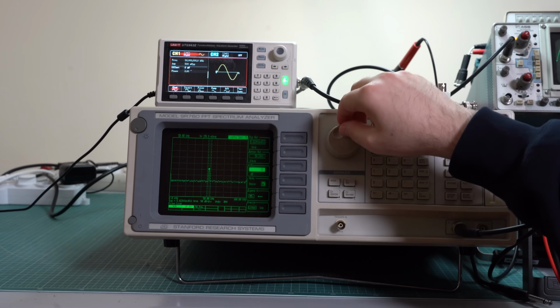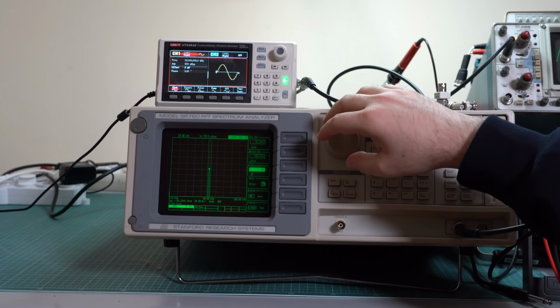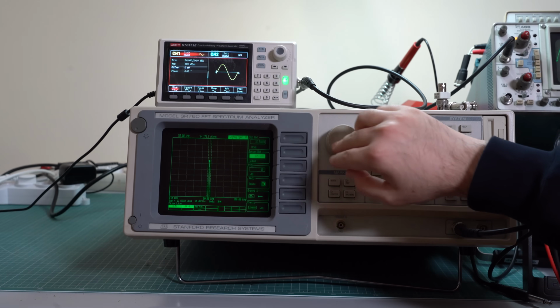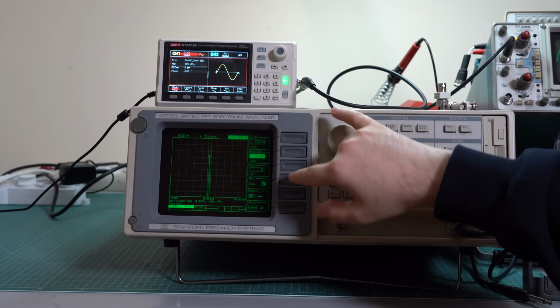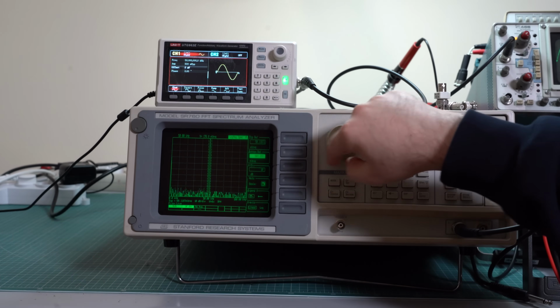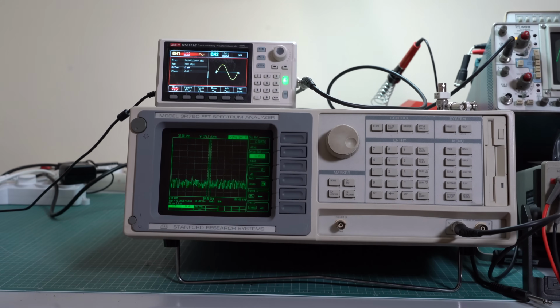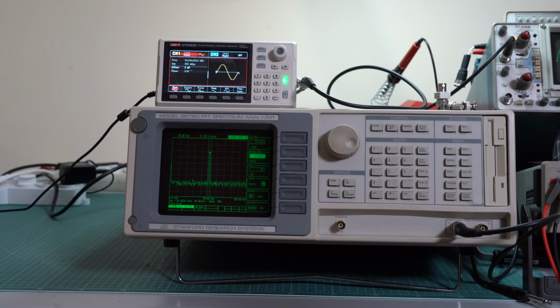So by increasing this number, as you can see, our peak gets really small. We can also decrease it, we can also move the bottom reference and so on, but now, as you can see, the dB per division is so low that our signal doesn't fit anymore. So we can either adjust it manually or just do auto scale, and it's adjusted automatically. And that's about it when it comes to the vertical scale, I guess.